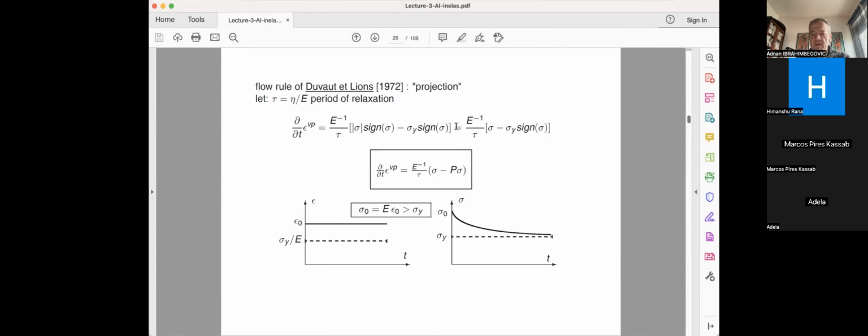And then basically you have this evolution equation again for the internal variable, which is here viscoplastic deformation, expressed in terms of all the variables, that's sigma, theta, and epsilon. At a certain point, now here already we dropped theta. Once we understood how to define dissipation, thermodynamics giving us this. For the moment, I just dropped the theta, and then we'll carry on without that, either considering that the temperature is fixed or entropy considered fixed. The thermal conditions are fixed or adiabatic conditions are fixed.